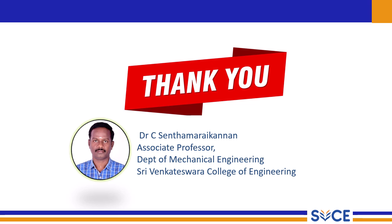Moving on, we explored piezoelectric transducers, which generate electrical charge and subsequently voltage when subjected to mechanical stress or deformation. Finally, we discussed electrodynamic transducers, which operate on the principle of electromagnetic induction. I concluded this video lecture with the LVDT, a transducer that produces an output voltage proportional to the axial displacement of a core.